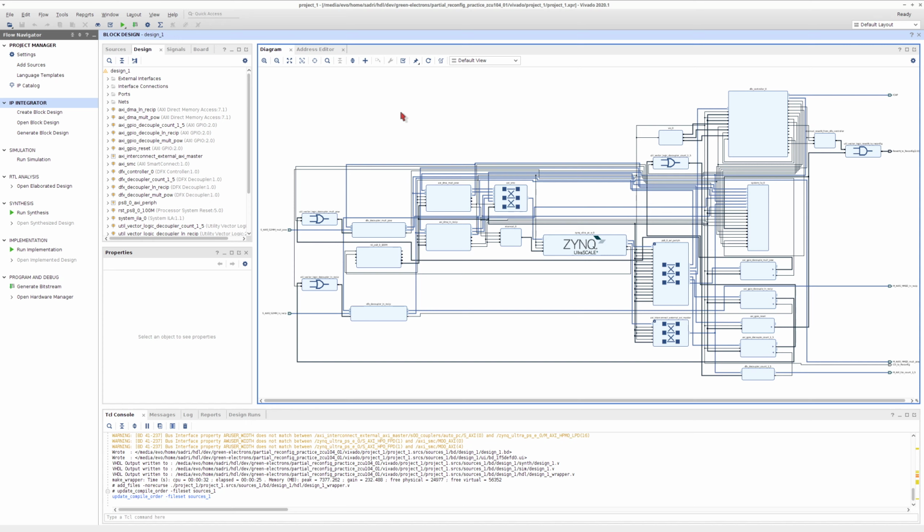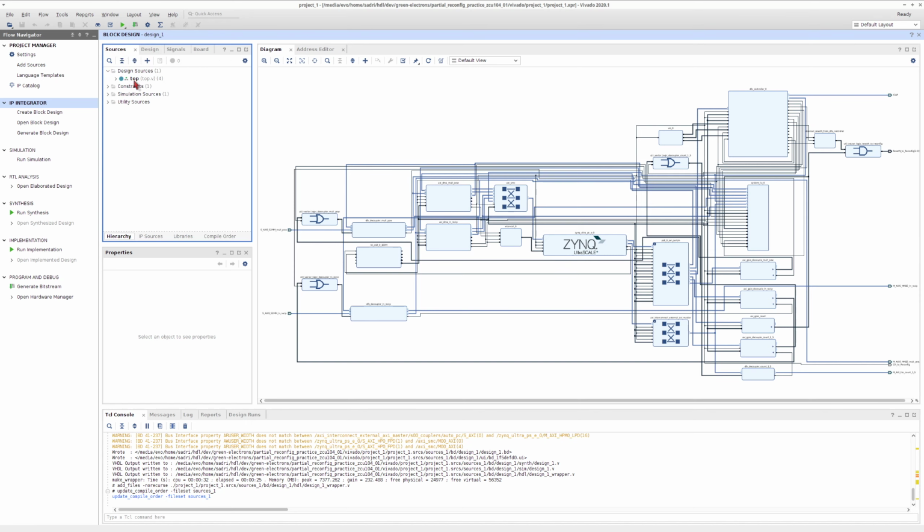Okay, so this is our Vivado project. We have seen this before. As I described to you previously, if you take a normal Vivado project, then usually the block diagram that you create is going to be the top level for your Vivado project. For the partial reconfiguration flow, currently this is not the case. You should have a top level file above this block diagram. Your reconfigurable modules should be instantiated inside that top level module. You cannot directly have the reconfigurable module inside the block diagram.